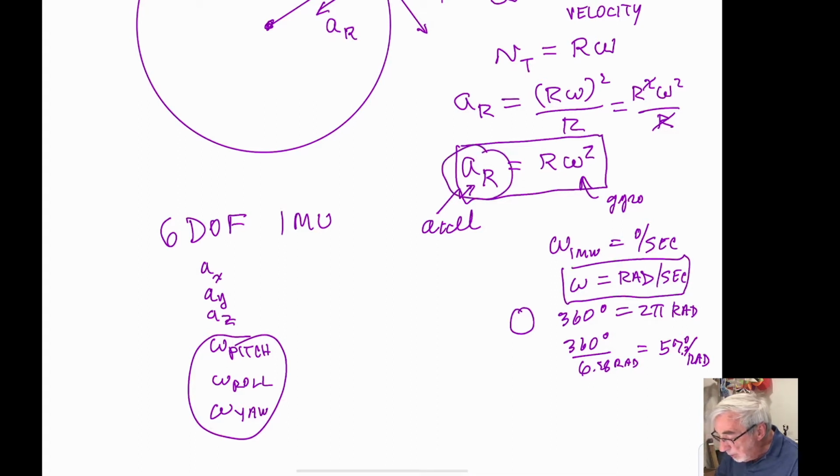The accelerometer gives us acceleration in units of g's, 1g, 2g, and so on. To convert g to meters per second squared, we multiply by 9.81. But actually we want to express it in centimeters per second squared, because that will give us a nice number to fit to the data.